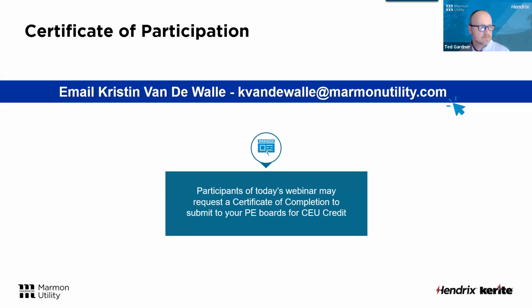Do we get any questions, Kristen? Yes, we had a couple. One we had already answered, but I will go ahead and ask this just for everyone to hear. There was a question regarding the difference in tree wire XLPE versus an HDPE jacket and whether one was tougher than the other. Our engineering response was that the thermoplastic HDPE is very tough and similar to the HD XLPE tree wire jacket. I just wanted to answer that one since that was in the Q&A.